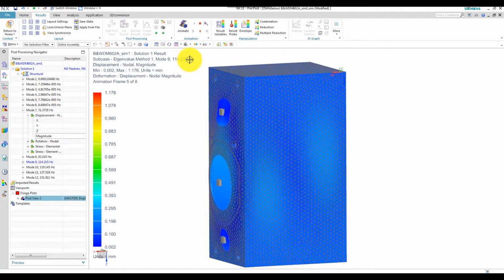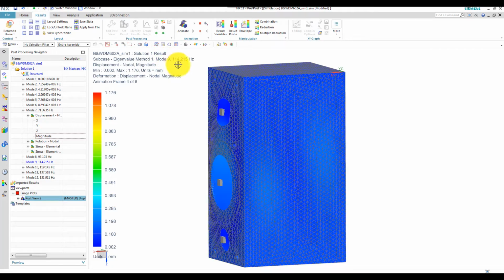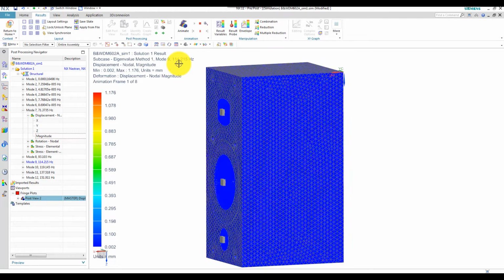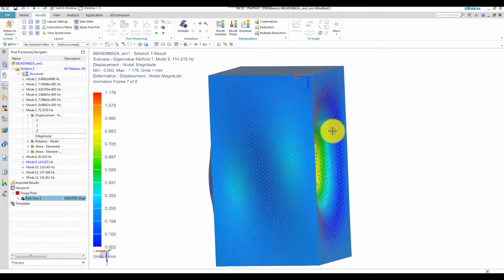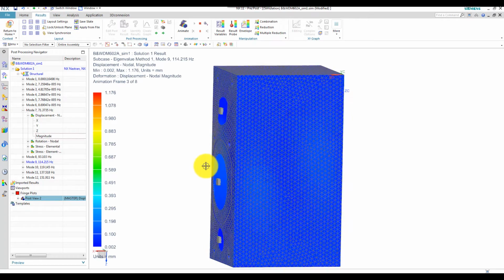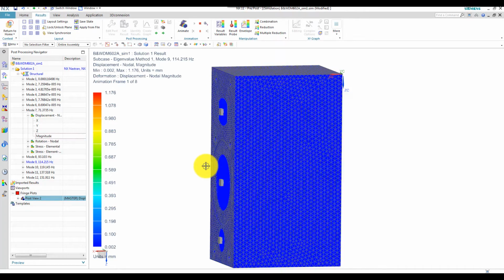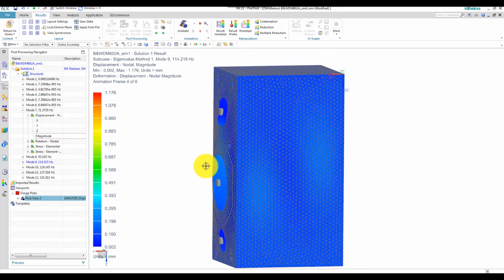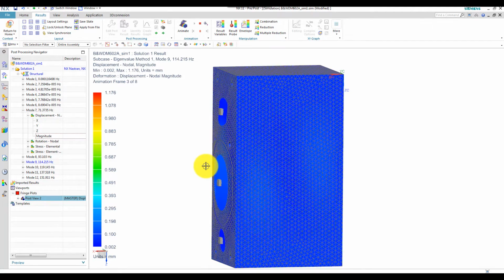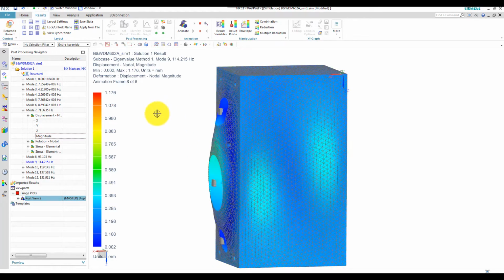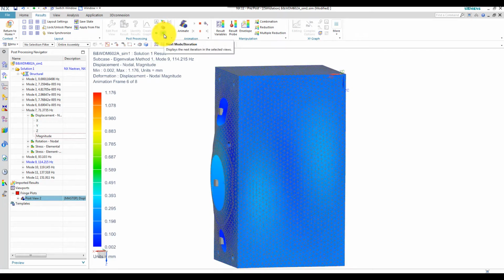It has an eigenfrequency of 114 Hz, which is quite coincident with the A2 string in the power chord. So I think we should make sure that both the rear wall and the front wall is reinforced. The question is how you do it, because you have to reinforce the front and rear wall so that the stiffness and mass ratio increases, because if you add too much mass, you have no effect really. But we see that we have at least 3 eigenfrequencies here, which is important. Let's check the next one.